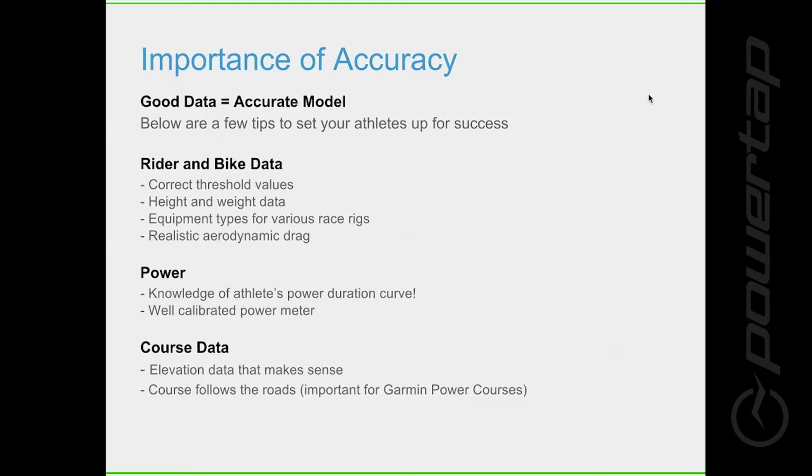For those of you who don't know a lot about drag, the equation is basically CDA. It's a multiplication, and the A part of that is area. So it's basically frontal area. What does the wind actually see when you're trying to fight it? And then the CD part of that is your shape, and that's fairly hard to quantify.